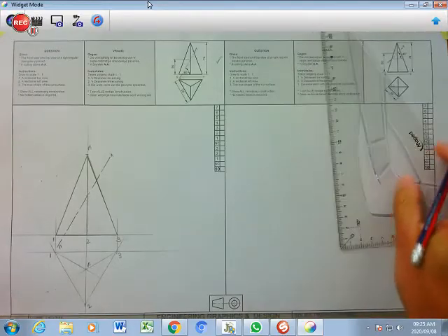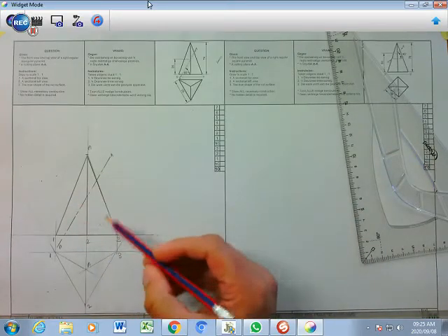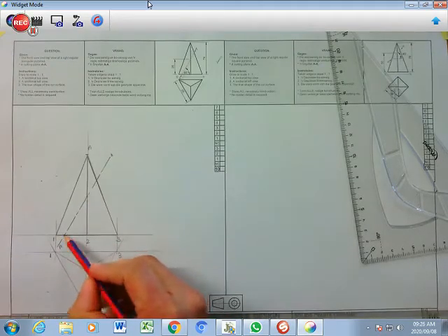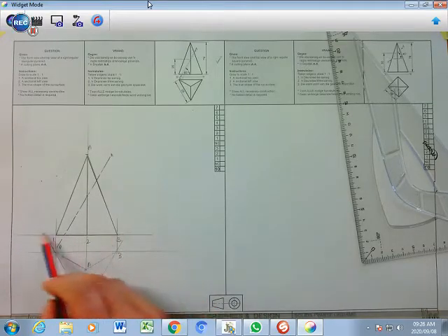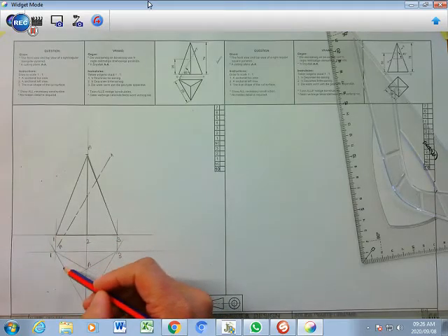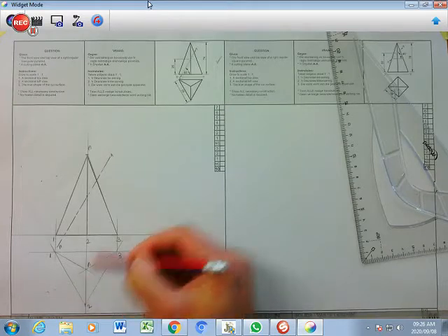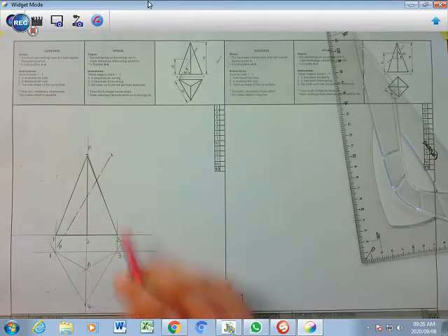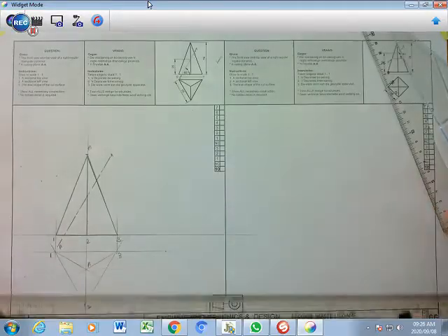Alright, so having that drawn dark, now I can do my cutting. So my cut section goes through there, at the bottom of my line there, it's going to cut through this base here, and that's going to cut on corner 2, and that's going to cut on corner 3. But just before I do the cutting, let me project a view here faintly so that I know.